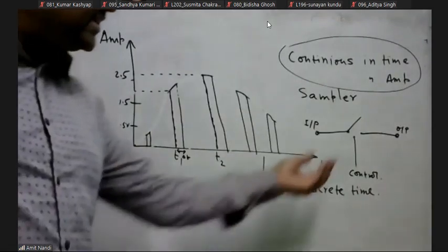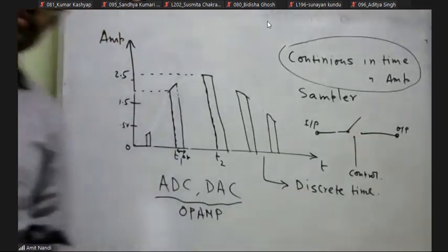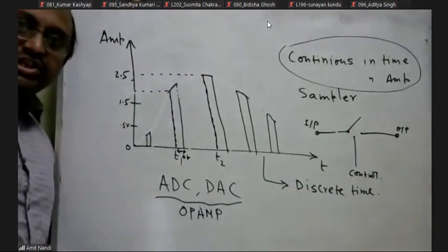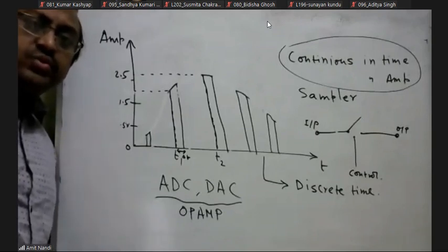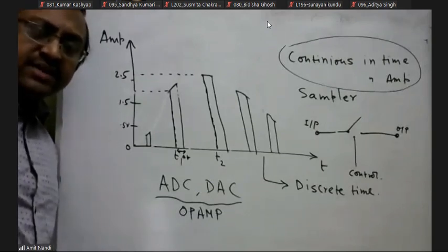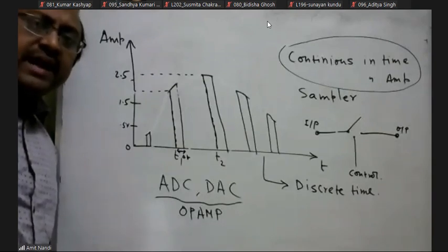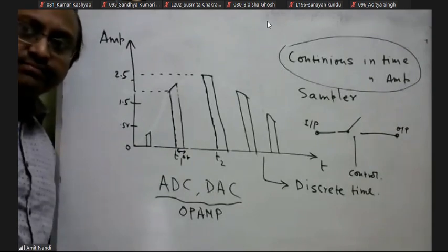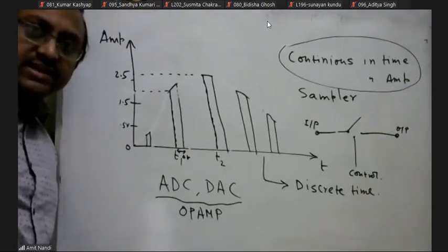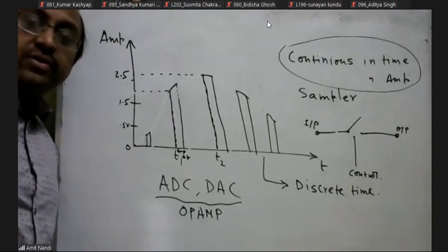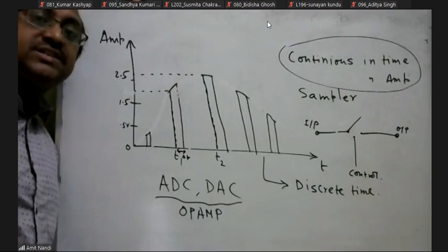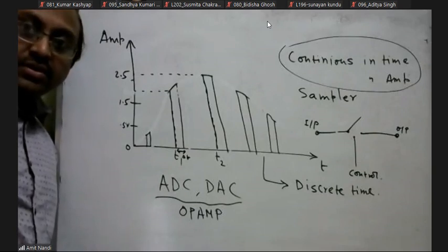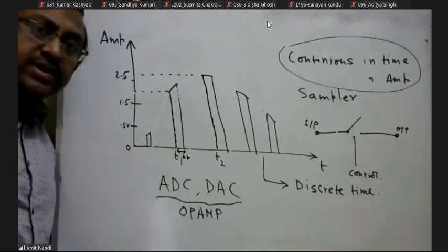If we need to build a sampler circuit, obviously we can use a diode as a switch. Sometimes we need to build an oscillator circuit using a diode. We can build a high frequency oscillator circuit with a Gunn diode or tunnel diode, so these circuits have different properties.